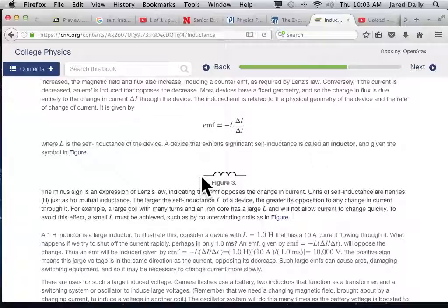That magnetic field is going through its own coil that created the magnetic field. And the magnetic field, as it changes going through that coil, actually creates an inductance in the coil. It actually induces its own current inside of itself. So this effect is even true on coils that are creating the magnetic fields. The magnetic fields they create affect the coils themselves. And this is called self-inductance.